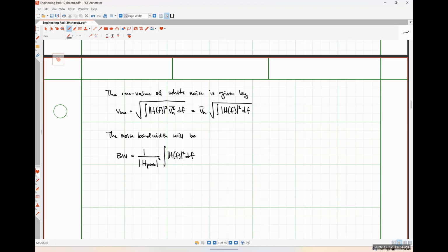The most common form of white noise is thermal noise. However, technically that isn't even really white noise, because at frequencies greater than about 80 terahertz, it starts to actually have a non-constant value. Luckily for us, that's way higher than most measurement systems can ever actually deal with. So we just treat it constantly as white noise.